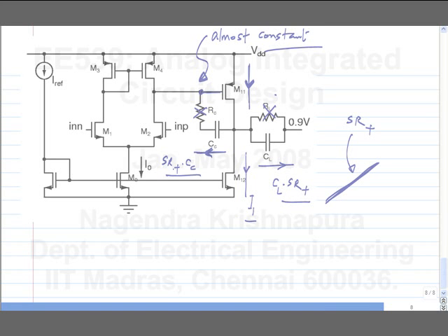What is the limitation here? Where is this current coming from? The current through CC? No, it is coming from this side. It has to go here, right? So it has to come from the first stage. What's the maximum current that can be delivered from the first stage? I0. Okay. So the maximum current available for discharging this capacitor, neglecting every parasitic here, is I0.